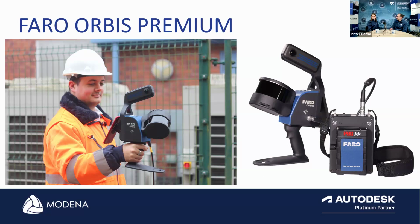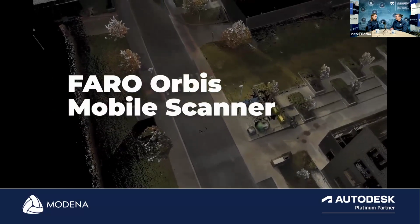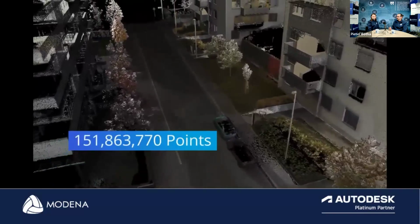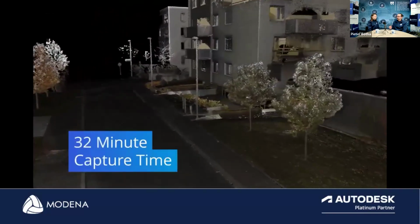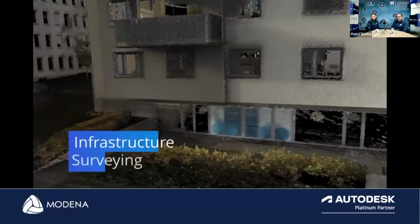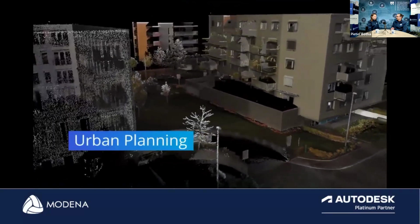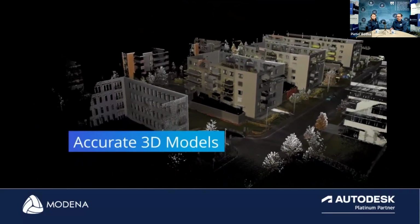Okay, so let's talk about the Orbis Premium. What is the Orbis Premium? The Orbis Premium is a SLAM scanner. So it's a mobile scanner where we can hold the scanner in one hand and walk the site. You don't have to run, or go very slowly. With that, you will capture 640,000 points per second with the Orbis scanner. It also takes an image that colorizes the point cloud, and you'll have that image as well at the end to view throughout the site that you have scanned.